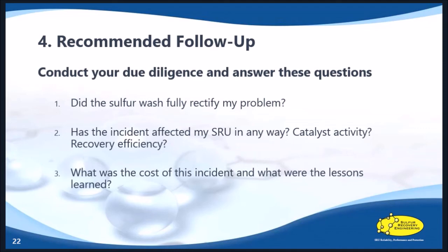Number 2, has the incident affected my SRU in any way? Theoretically, like we said at the beginning, there shouldn't be any change. The procedure itself should be non-invasive, you could say, to the catalyst activity, to your recovery efficiency. But the incident itself may have done something to the catalyst. The incident itself may have done something to your equipment. Now you need to ask yourself, how do I check to make sure those things are not occurring right now, that I'm 100% safe coming out of this procedure, coming out of this incident.